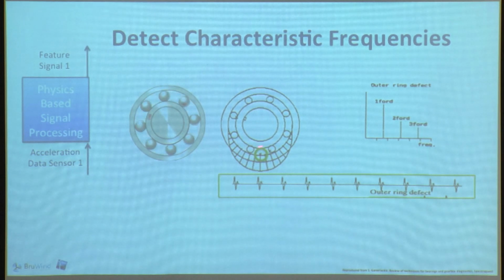If I have a crack in the outer ring, what will happen? The rolls will pass by. You will see the crack, so you have this impulse, tack, tack, next roll, tack, tack, and so on. Because you are in the load zone, the force here doesn't change. The rolls are pushed onto this crack all with the same force, so they will give a similar response.